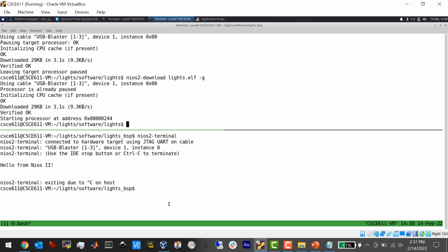But in this class, we're still going to use the performance counter basically as a clock. It's just a counter that counts every clock cycle, and it gives us very fine-grained measurement control. We can measure time down to a 50 millionth of a second because that clock ticks every cycle, and the clock is running at 50 megahertz, right?